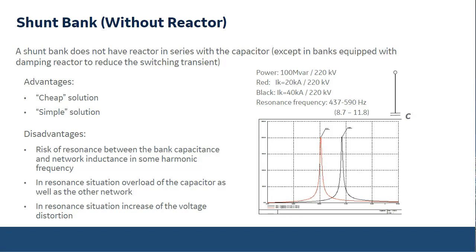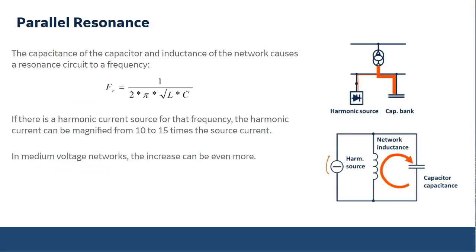This means that when you have the 11th harmonic there, this will amplify it quite a bit. So you will have a resonance with it. This is not a very good solution in this kind of application. Here are then more about the resonances. So now we have the resonance here.